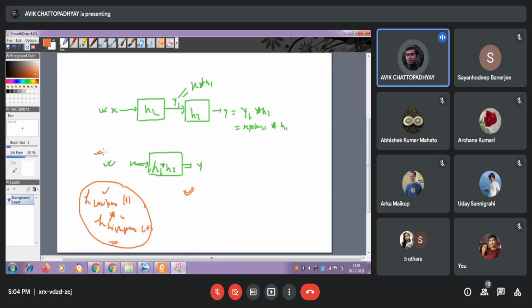So in the background, what is running is the convolution. So what is true for convolution is equally true for an LTI system. Or in other words, the way we do the convolution operation, the expression of convolution we derive, we only exploited the properties of the LTI system. So whatever is true for the convolution has to be true for the LTI system.